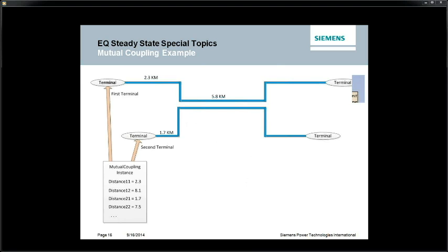Fault analysis, the fault package, is where you can define a fault at a location and give the fault impedances and whatnot. So basically, you've got a class that describes the fault, and it describes the impedance at the fault at this particular location, what kind of fault it is, whether it's line to ground, line to line, or line to line to ground, and which phases are involved.